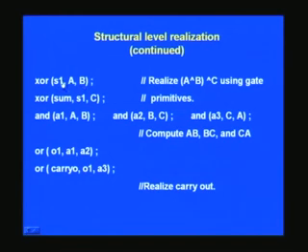As I mentioned, they are normally restricted to 2 inputs, and some offer higher inputs as well, but that is not guaranteed on all platforms. And finally you plug this into the next exclusive OR along with the third signal which you have not used earlier to get the final sum output here.